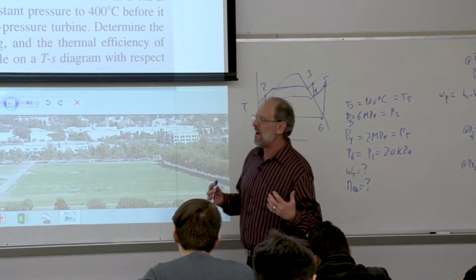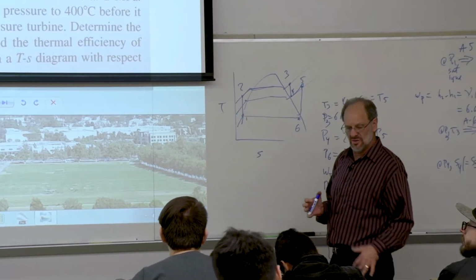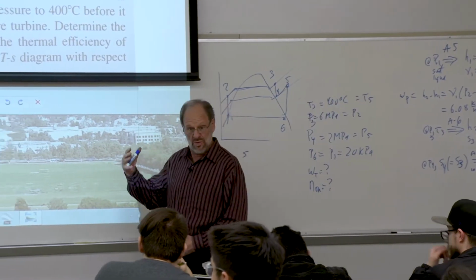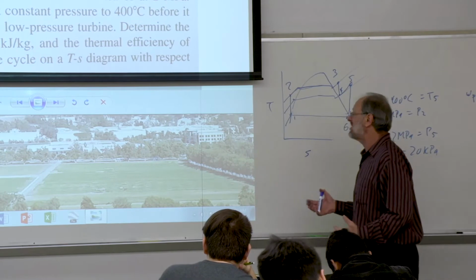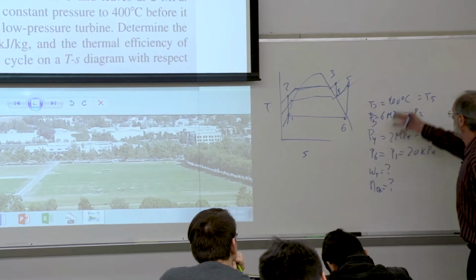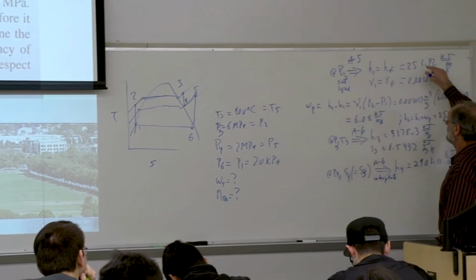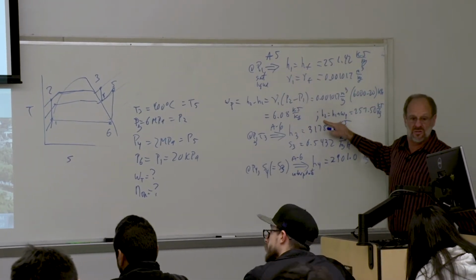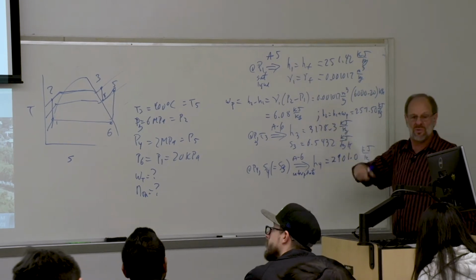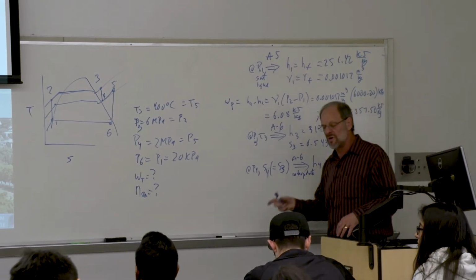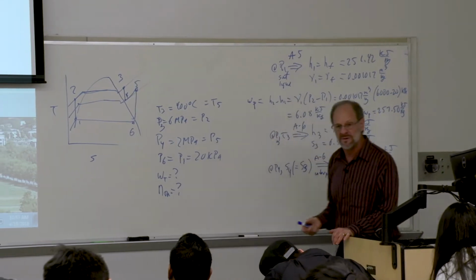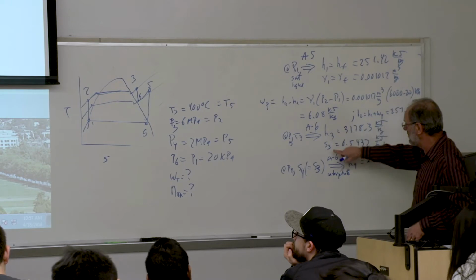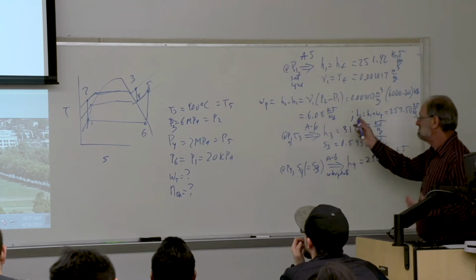So there you have another problem that is specifically the Rankine cycle, but the ideal Rankine cycle with reheat. Now, if we had the same problem but with a non-ideal turbine and pump, it doesn't change things a lot. I mentioned briefly before what we do, but let's just talk about it briefly again. Here, this term would not be H2, we'd call it H2S. And then we'd apply the isentropic efficiency, which is H2S minus H1 over H2 actual minus H1, and that gives us H2 actual.